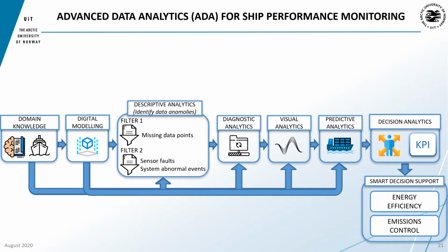So, what is Advanced Data Analytics (ADA) for ship performance monitoring? Domain knowledge and digital modeling play important roles under ADA since they interact with a number of analytics layers such as descriptive analytics to identify data anomalies through two filters. Filter 1 due to missing data points, filter 2 due to sensor faults or system abnormal events.